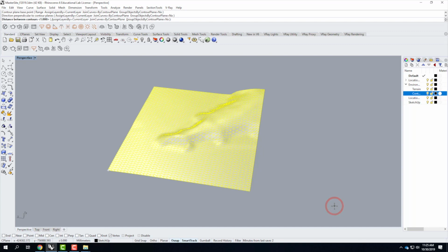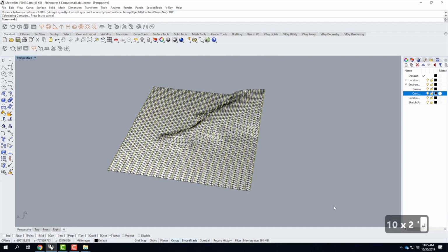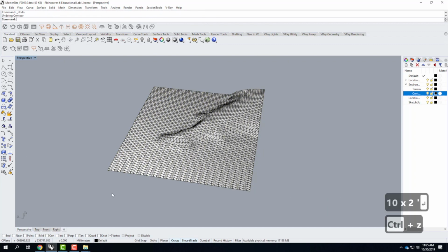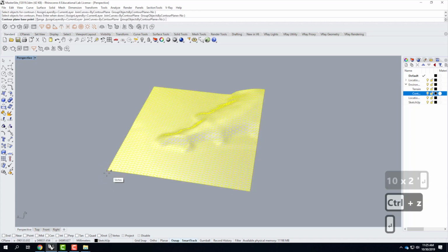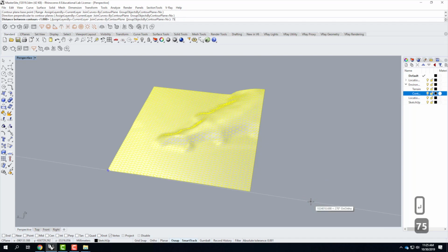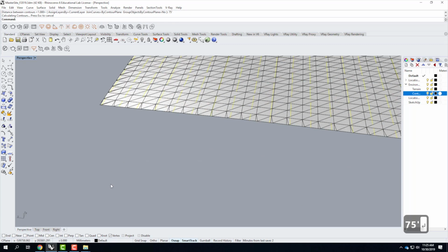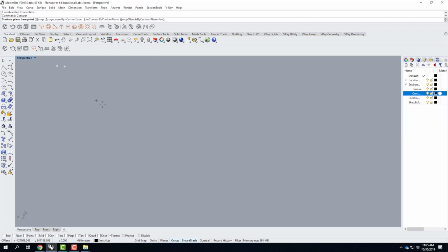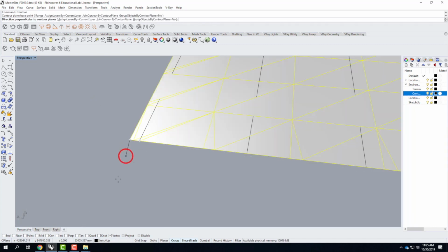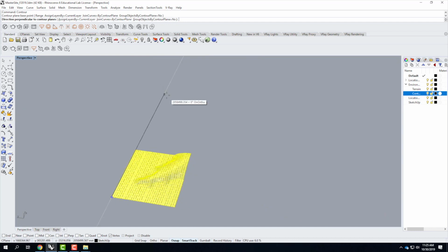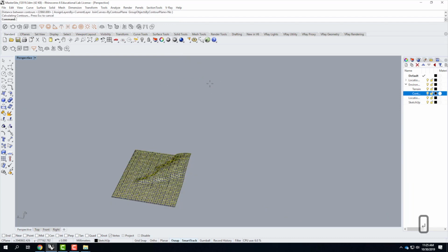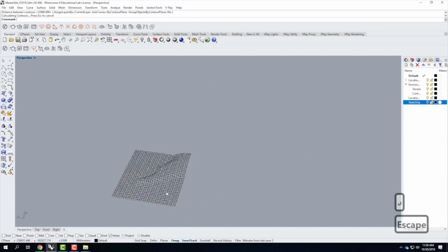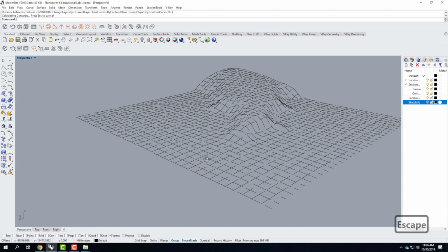We're going to go straight in the X direction here. I'll do it at 100 feet. And it needs to be a little tighter than that. I'll try it at 75 feet. That looks a little better. And remember, I'm going to contour the surface only. And we're going to go in this direction this time. Same 75 feet. I can then turn off the SketchUp layer, and it leaves me with just my grid.